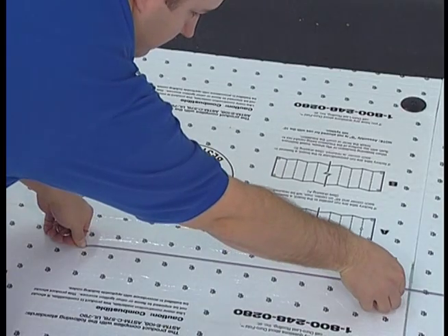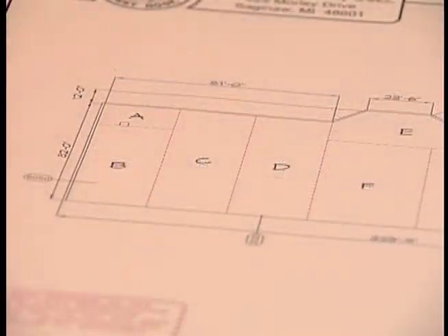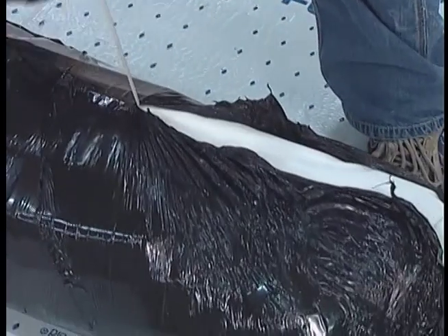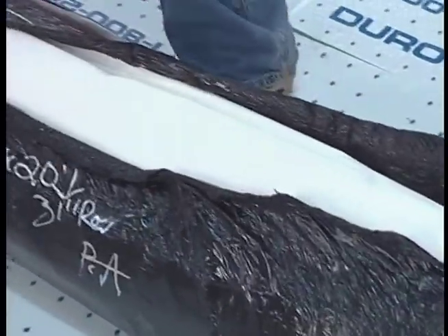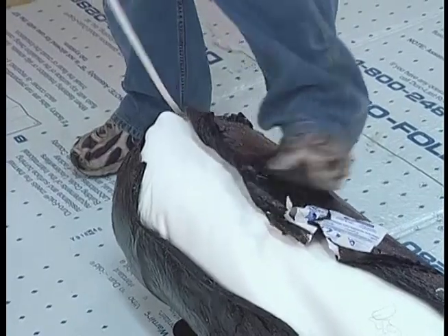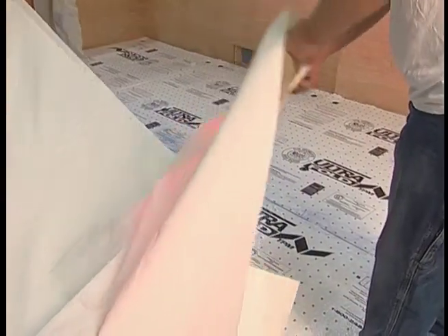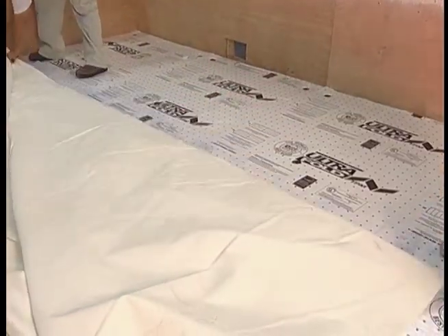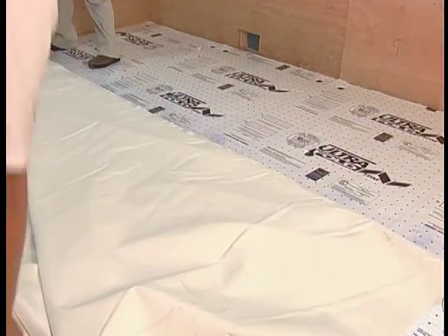Now, snap your line. From the roof layout diagram, determine the correct roll to be used and move it into place. Position the roll so that it will unroll from right to left. Remove the plastic wrap by jerking on the ripcord and unroll the Duro-Last membrane so the exposed tab is close to the chalk line mark.